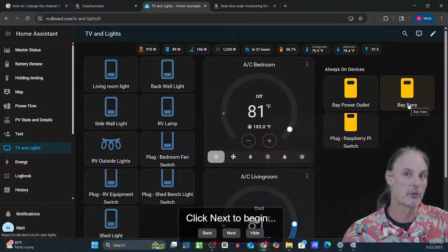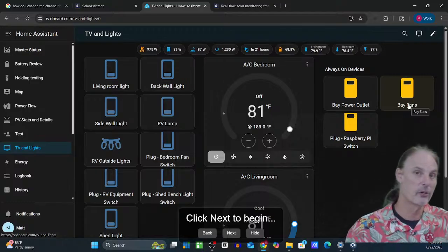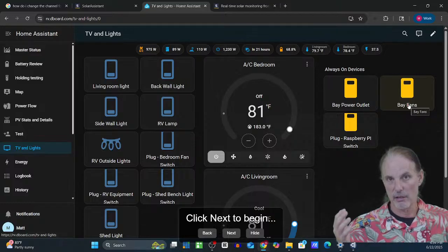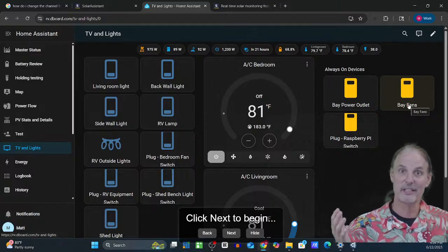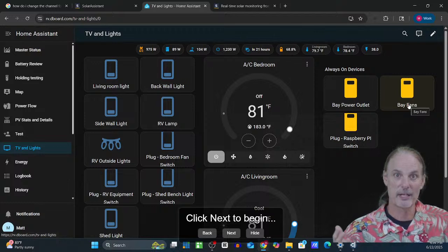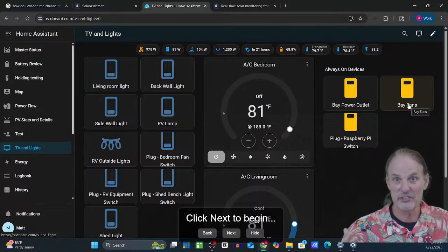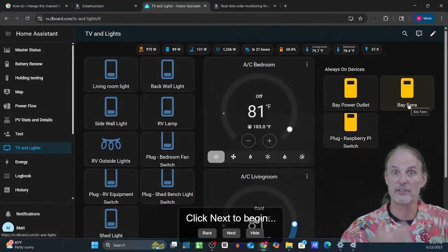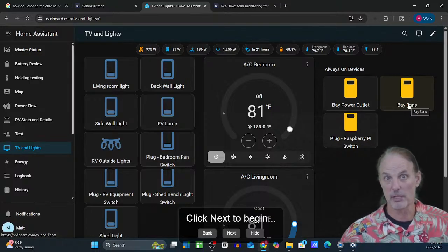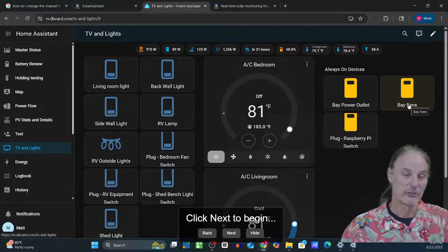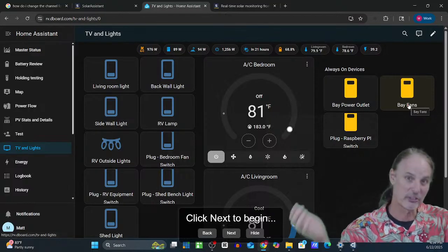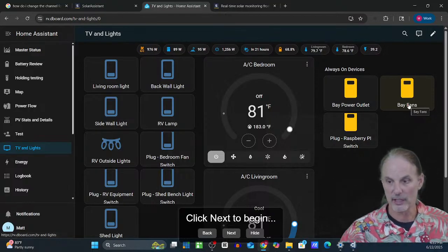It also allows me to control them based on humidity. I live very close or right on the river here in Florida. It basically allows me to say, look, in the early spring and late fall, if the humidity is extremely high in the morning, to turn the fans off and let the inverter's heat bake out some of that humidity, so I don't run into problems with humidity, by automating whether or not that fan is pulling that air out or leaving it in.